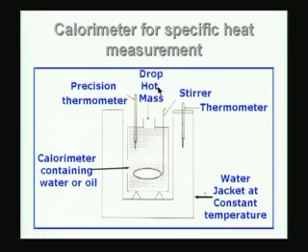So, the experiment is very simple. You take a certain amount of the material, usually in the form of beads or pieces, whose thermal specific heat I want to measure, and heat it separately in a different environment. For example, you can put the material inside an oven, bring it to the desired temperature and immediately transfer it by dropping it into the calorimetric vessel, and immediately after dropping you start noting down the temperature as a function of time. So, from the time temperature graph we will be able to estimate the specific heat of the material which has been heated separately and then dropped.